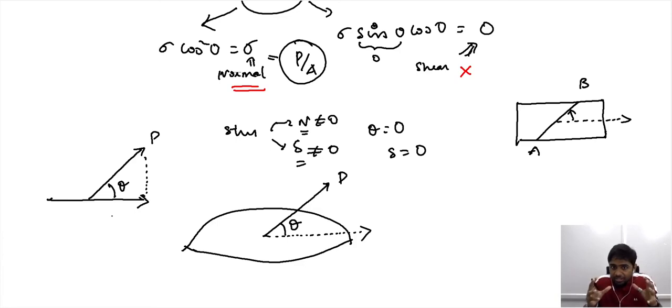However, when your region of interest is an actual plane, in that case we have restricted ourselves to a specific direction because this theta here is different from what would be the theta along this direction. Even though this direction also is on the same plane, the angle that this vector makes with this direction here will be different. The same goes for the angle this vector makes along this direction here, the same goes for this direction here. So essentially, in this case, it is rather straightforward for us to have a given theta and then to state that this is the stress that is acting along AB.